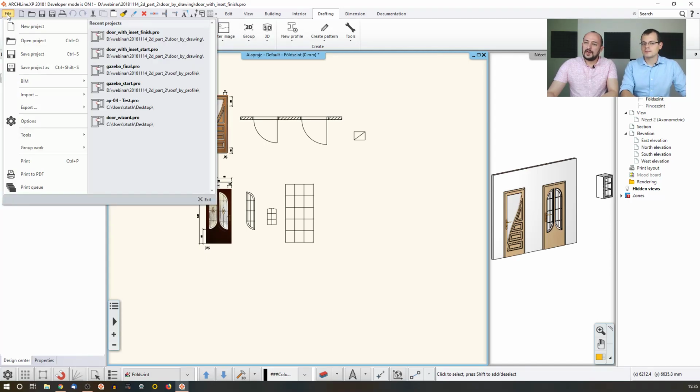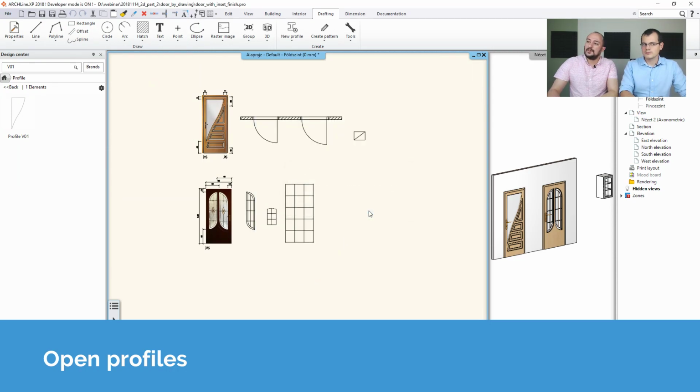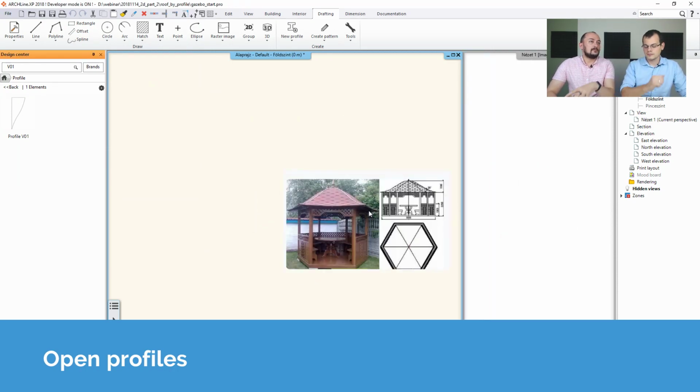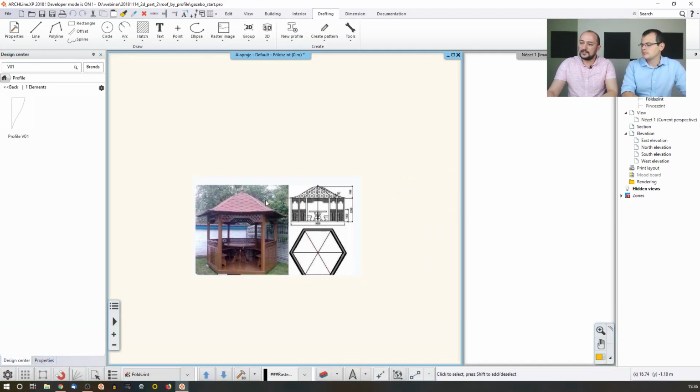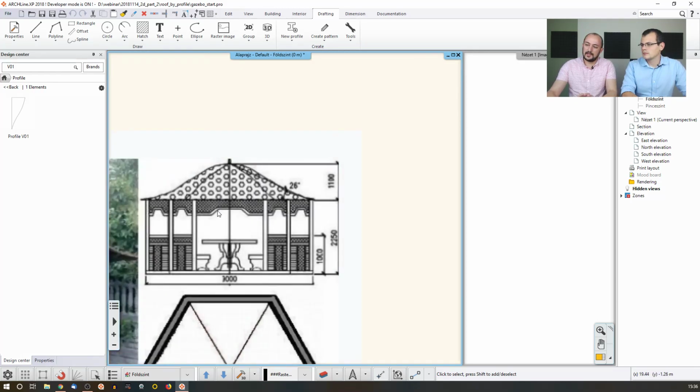Well, a classic open profile can be demonstrated using a gazebo roof, or we could use another example, like a revolved object, like a glass or a mug. When you're using the Revolve 360, the solids of revolution, that is also an open profile. An open profile is classically demonstrated here. I have a photograph of this gazebo roof with the underparts, and a frontal view with all the measurements, so I scaled it up, and this is how I got this result.